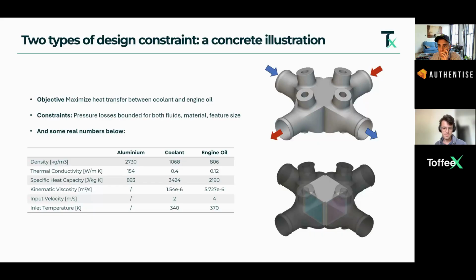It's a very simple example of a heat exchanger, and it doesn't really capture the full complexity of a real automotive oil cooler. But essentially, in a heat exchanger, you've got a hot side, in this case engine oil, and then you've got a cold side, in this case a coolant, which is probably some sort of propylene glycol mixture.